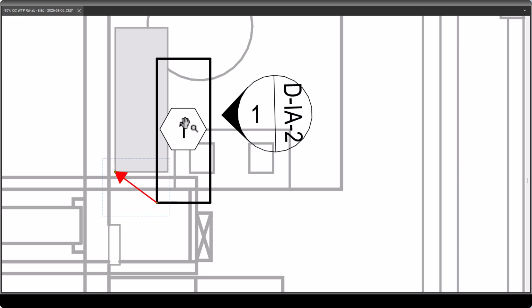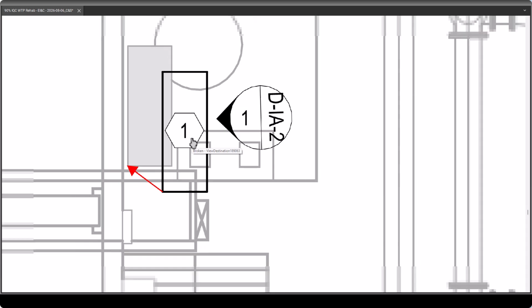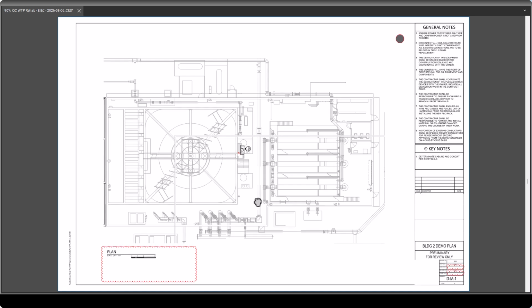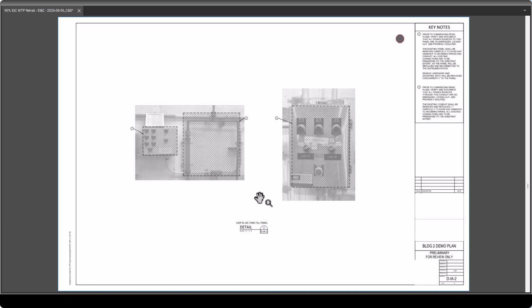One thing I did catch on mine, I have a mix of keynote symbols. Some of them are legacy and don't have the background, so you would be able to see lines behind here. Some of them are current and do have the whiteout. And if you can't read the keynote because it got printed off and there's too many lines in the back, that's a problem. And that has happened on multiple occasions. So it's small things like that. And I know it's kind of hard on a project like this, but yeah.